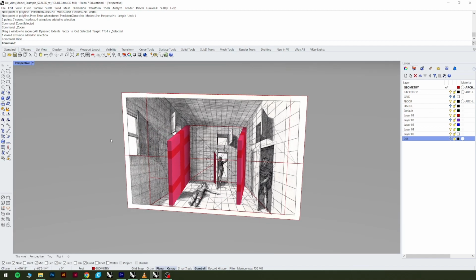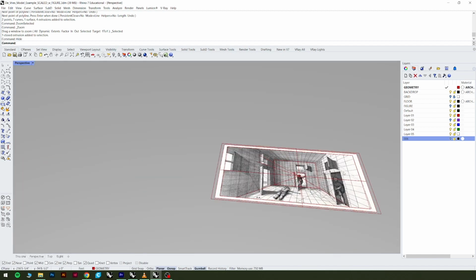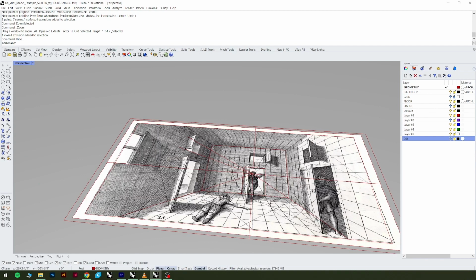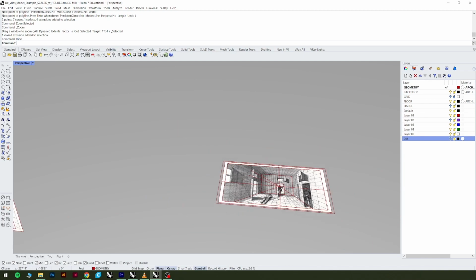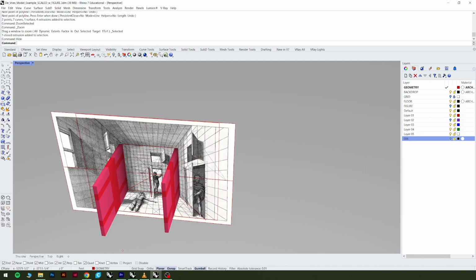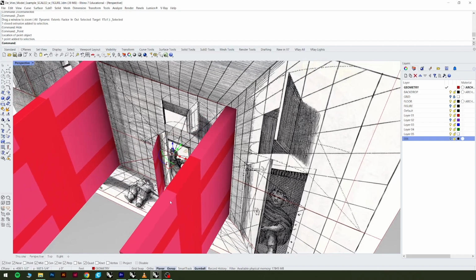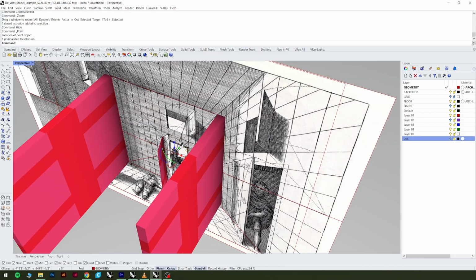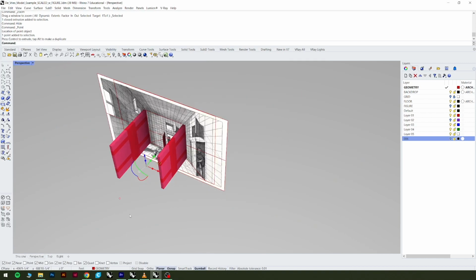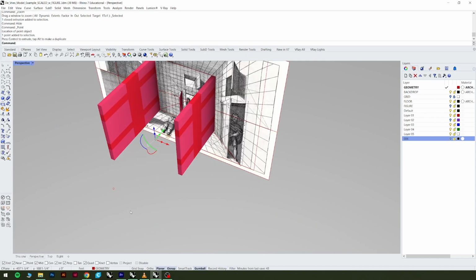So to do that, I drew the horizontal line and that vertical line, and then I'm going to place a point, which I already did, at the intersection of those. So there's that point right there. And then I just use the gumball. I grab, in my case, the green arrow while holding Alt, and I can drag a copy of it, as you well know by now. I'm going to delete that one because I already did it over here.